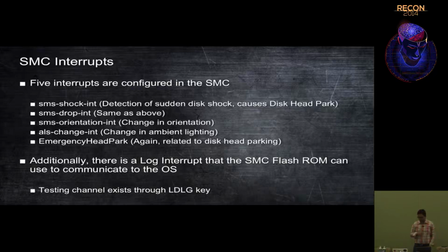So I don't have a video of that. After this, I'm going to try the output one more time. But with the new SMC, you can actually write into the kernel printf log from the SMC. So I was able to flash a little bit of code while experimenting that actually printfs. And instead of printfing in some weird debug log that I need a hardware programmer to access, it actually printfs into the root kernel console. So basically, from the SMC chip, I can reach out all the way to the driver and have the driver printf something, which is obviously really useful for debugging.